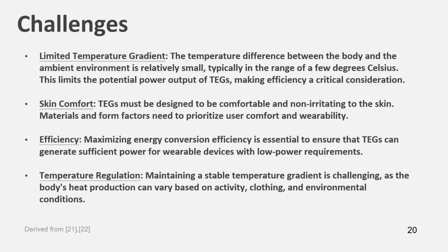So coming on to the challenges faced while advancing in this domain, one of the challenges is the limited temperature gradient. The temperature difference between the body and the ambient environment is relatively small. We have already discussed details regarding that. It's a maximum of 15 degrees Celsius which exists between the human body and the atmospheric temperature. So typically this limits the power output potential of TEGs, making efficiency a critical consideration. So the TEG efficiency should be modified accordingly to work at lower temperature gradients. And the second challenge is skin comfort. TEGs must be designed to be comfortable and non-irritating to the skin. Materials and form factors need to prioritize user comfort and durability.